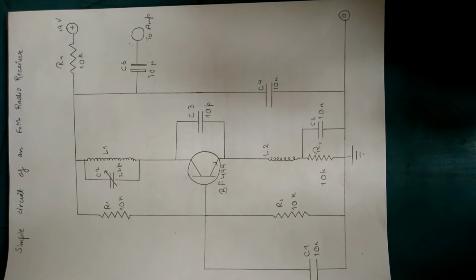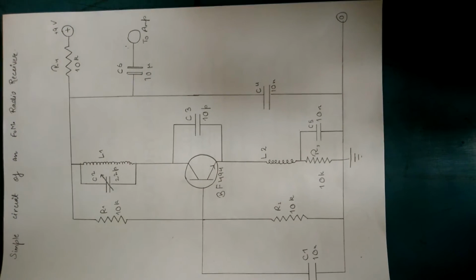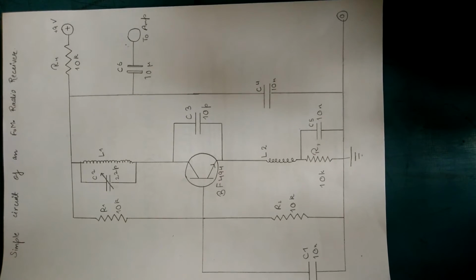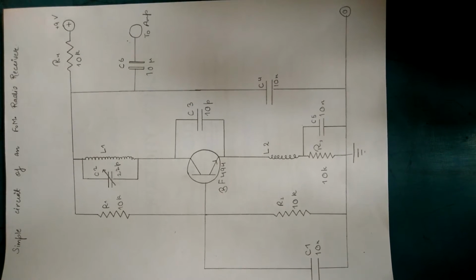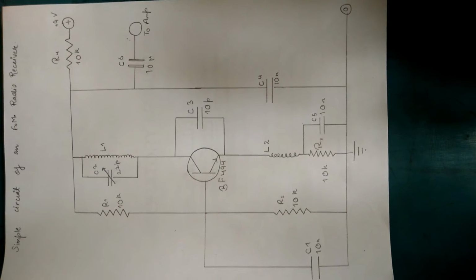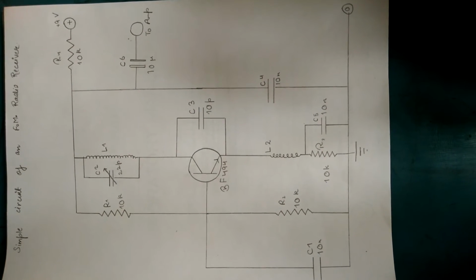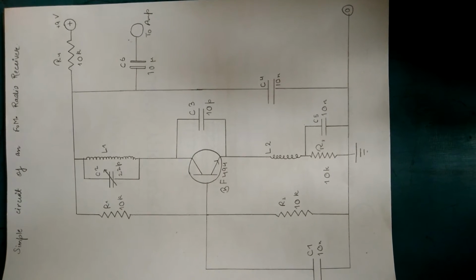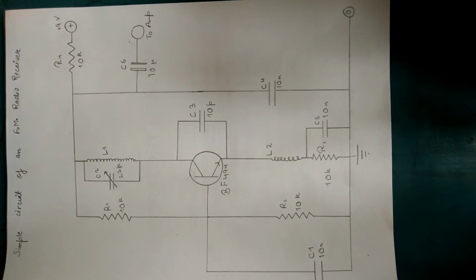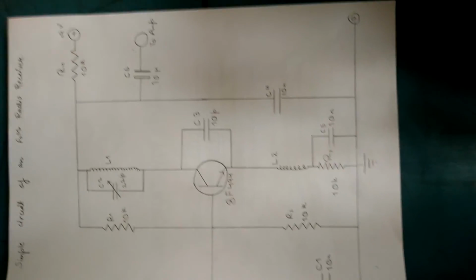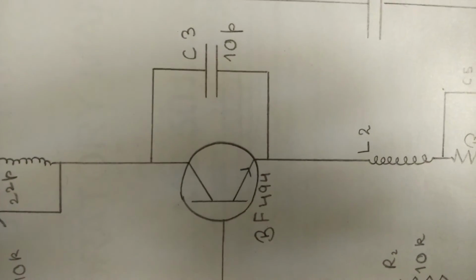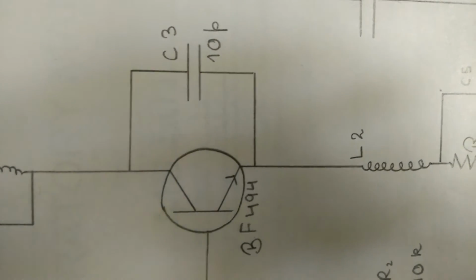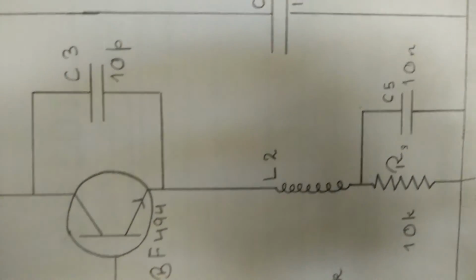As mentioned above, the circuit is basically a single transistor super regenerative RF oscillator with a constant amplitude. Here we have tried to enhance the design such that the amplitude becomes considerably magnified in order to turn off the transistor completely during the oscillations. This calls for an increase in the feedback capacitor and also the use of a transistor specifically designed for handling extremely high frequency ranges, such as BF494. Further modifications include an inductor with the emitter of the transistor and a capacitor across the emitter resistor of the transistor.